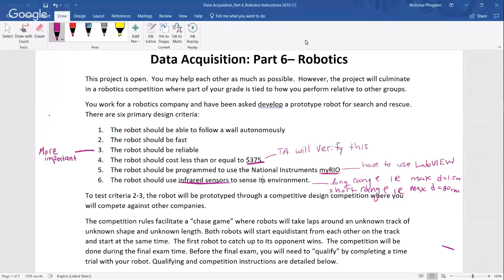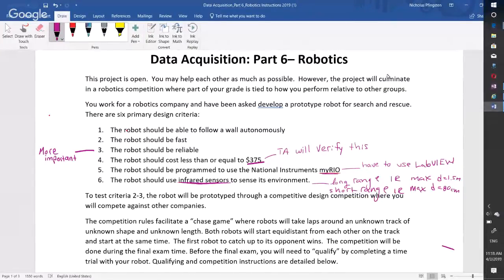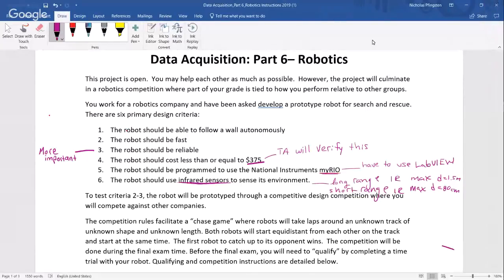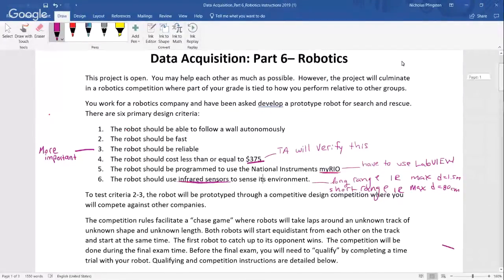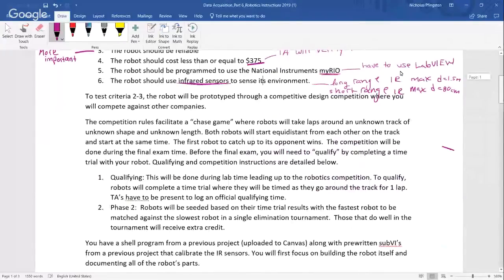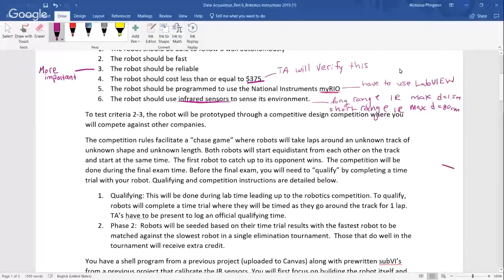That's the usual ratio. Yeah, so you know the graph goes up and then down, and you know when you calibrate it, you try. So it's like tolerance. Range. Okay, that's the blind spot. So when we're using IR sensors, we try to avoid being in the range of the blind spot. This particular application actually doesn't hurt you too much, the blind spot, because if you're close, it overestimates the distance. All right?